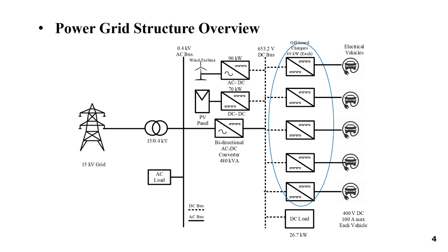The most popular and commercially available off-board charger is for 40 kilowatts, and the ampere range is 100 amperes. The levels established by the Society of Automotive Engineers all place the stated off-board chargers above level 2, which is the lowest level, since they can fast charge. They are classified as level 3 vehicle supply equipment.